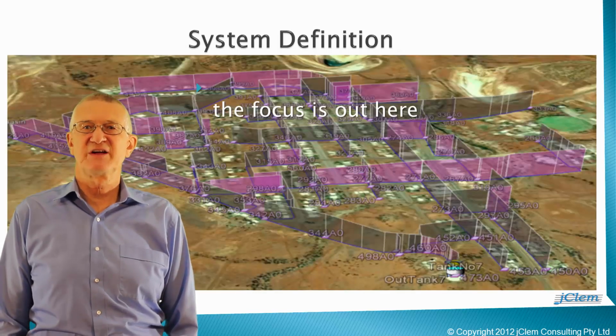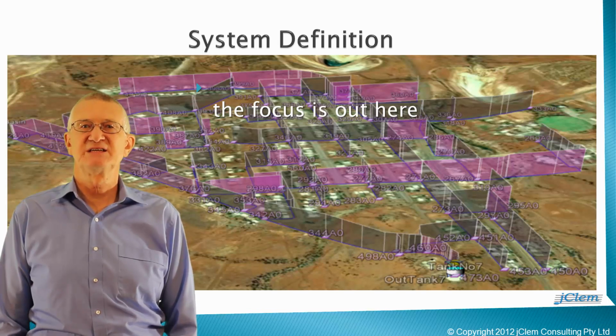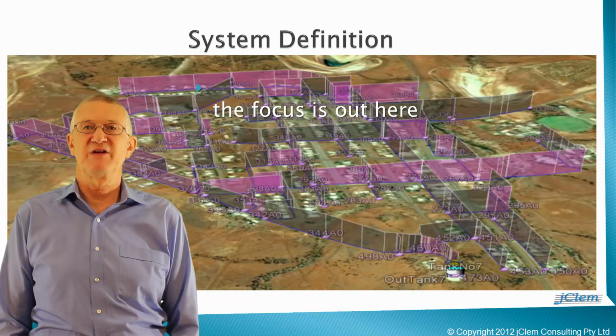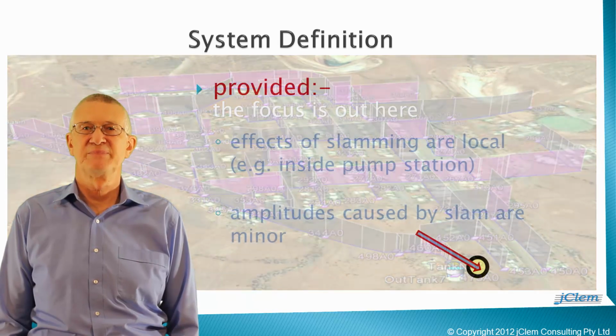An additional justification for initially assuming perfect non-return valves is that until the overall system surge protection is analysed, sized and located, the overall system is not yet defined. For example, until it is known whether pressure vessels are needed on the delivery side of a pump station and the amount of energy to be stored in their compressed air volume, the potential for the system to generate reverse velocities through the pump station's non-return valves is not yet defined.